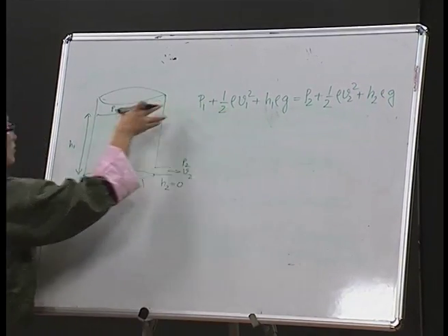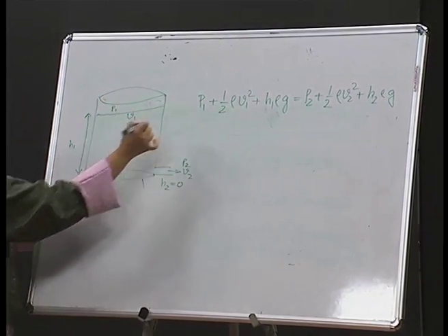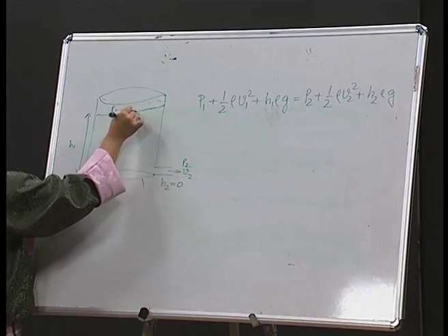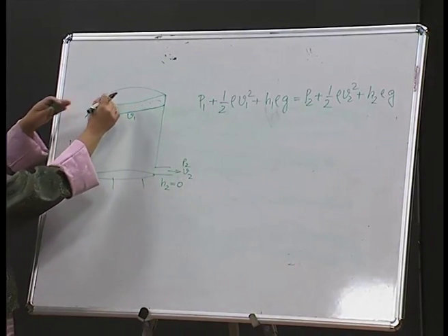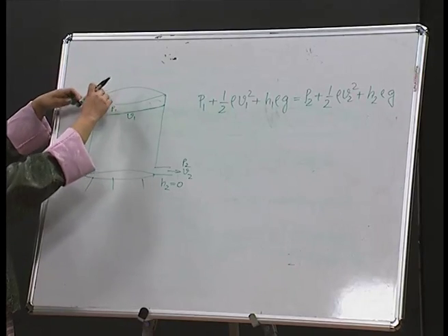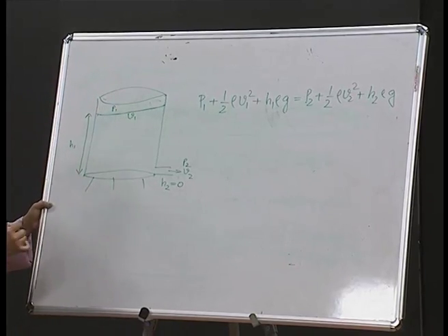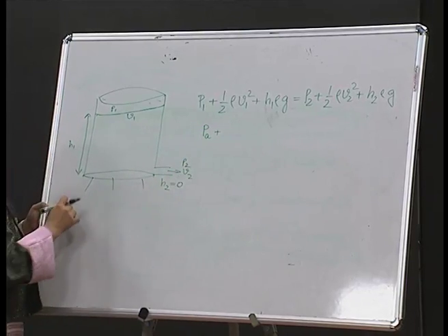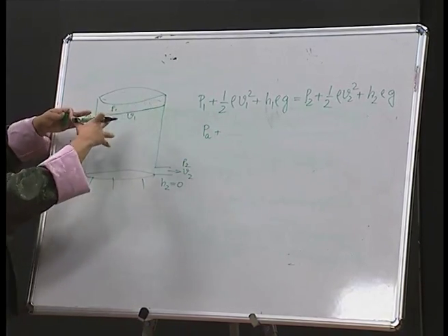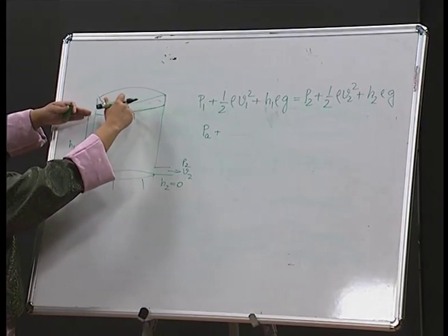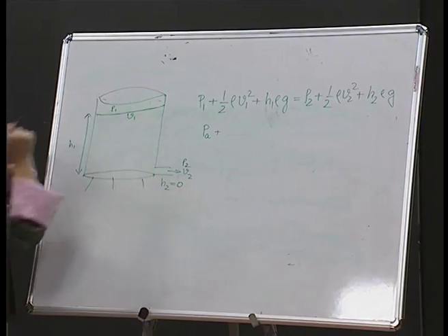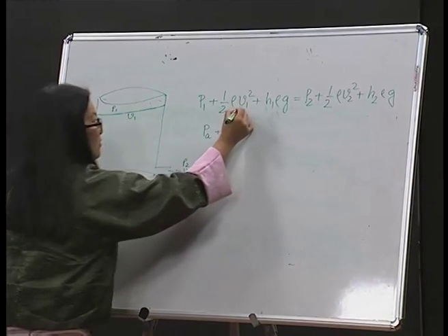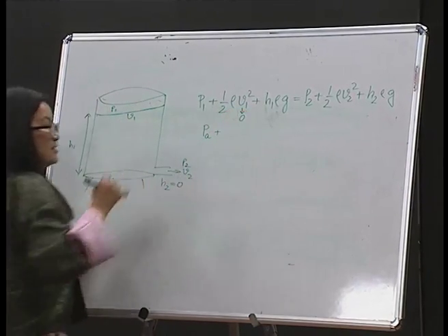So, this is for the upper height here, pressure P1. Now, since this is open, we are going to take pressure due to atmosphere. We call it atmospheric pressure. So, let me write it as PA. And now the volume of water is so much that the velocity with which it flows is negligible. So, therefore, V1 I am going to assign 0.